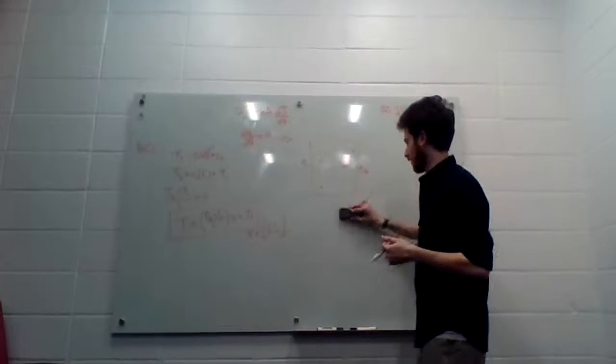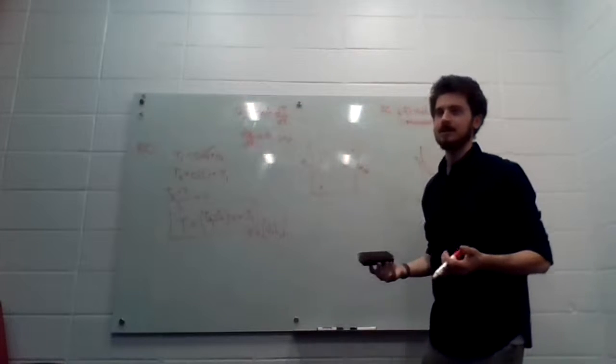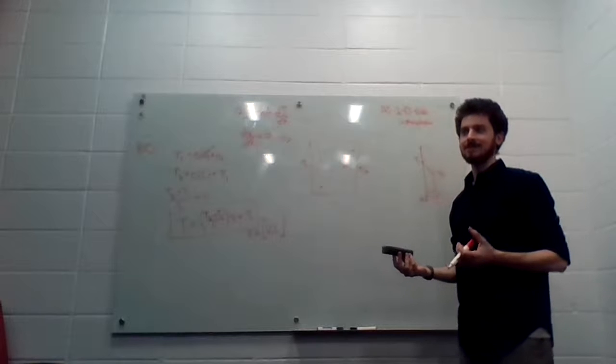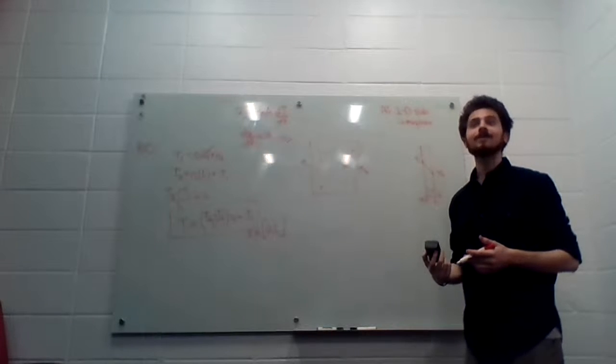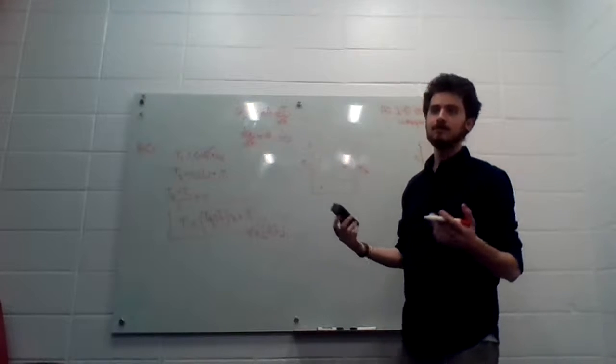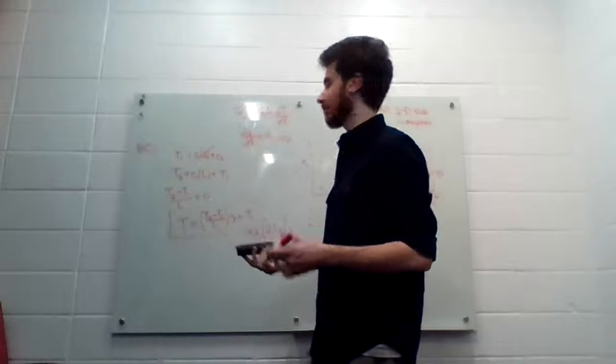Now, I used to be a practicing engineer. What tells me thermal conductivities is ASHRAE Fundamentals 2013, which has a great reference table in the back that says if you're doing gypsum board and glass and this and that and the other thing, these are your thermal conductivities, and that's how you get your resistances.